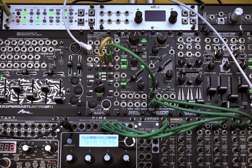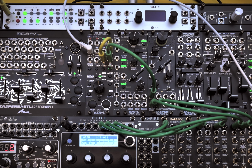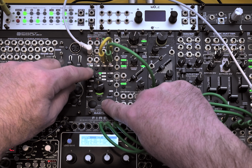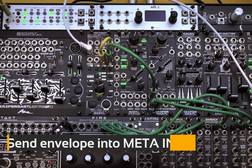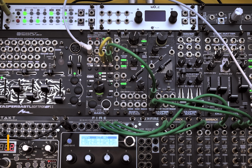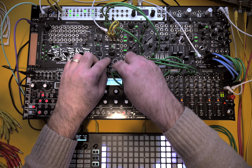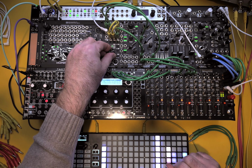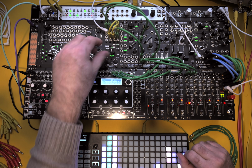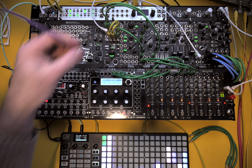Now, how about creating envelopes? Where would I get the envelopes from? Well, we know we have an envelope generator. So let's go into channel D. You can see here it's an envelope mode. And what I need to do is map the meta in for channel F to be a VCA. So I go back to channel F, I select it here, then we press shift and mode, and we see it's in LFO VCA mode. So meta in is now mapped for channel F onto being a VCA, which means an envelope there will sound out the oscillator. So let's create an envelope, and we'll do that on channel D. I'm just going to patch the output of channel D into that meta in. And of course, I could patch in an external CV into this channel E quantizer.